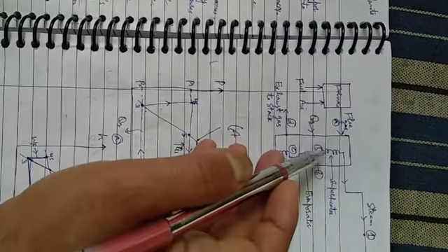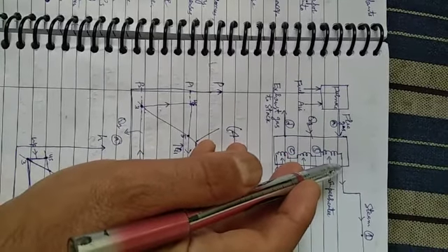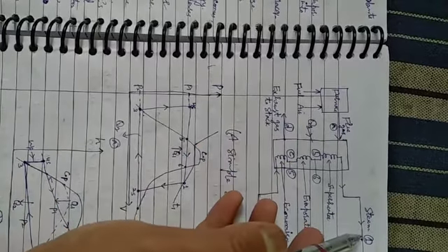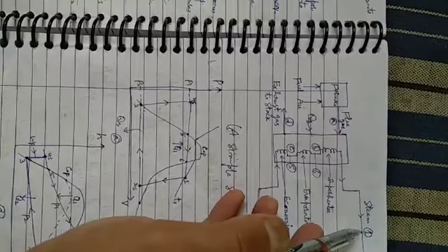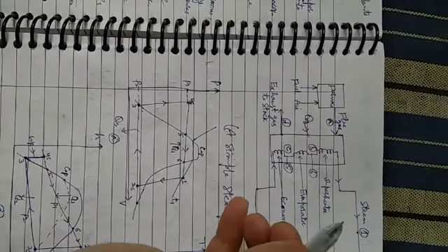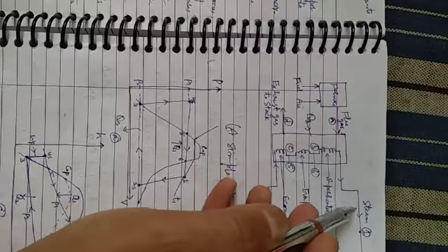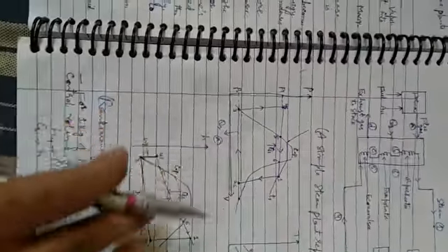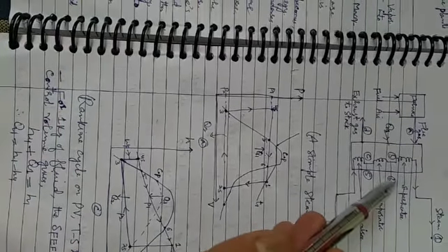After point 6, it is further heated, superheated. It is called a superheater. It is further heated until the steam is in the purest form in the superheater. Then at point 1, we have pure dry steam, which finally enters the steam turbine. So after the superheater we get the purest form of steam. You can see from my notes the function of the economizer, evaporator, and superheater. These are three parts of the boiler.